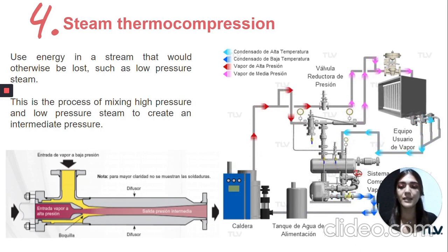The compressed steam is pushed into a chamber with a lower temperature, and consequently it condenses. It gives up its heat of evaporation to the liquid contained in the condenser, and the liquid evaporates in an amount that corresponds to the weight of the condensed vapor.